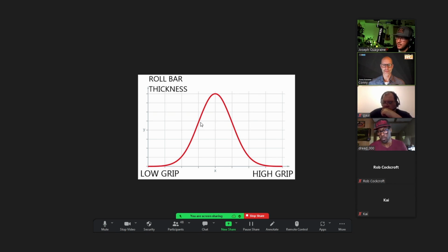So then instead of limiting the movement with roll bar, what you would do is you go to really thick damping instead. You make the shocks thick, and you slow down the roll so much with the shocks that in those sections of the track, the car doesn't have time to roll far enough. So it's something I'm going to try next time, actually.